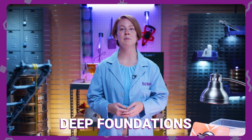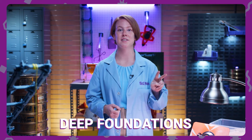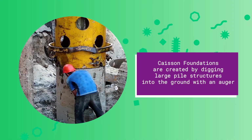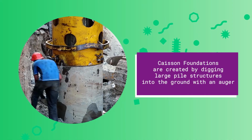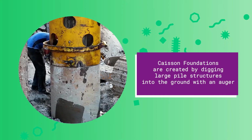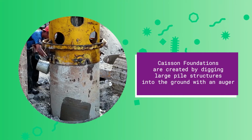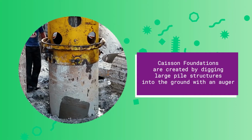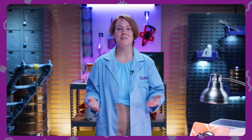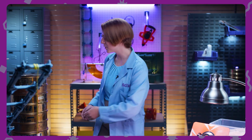Deep foundations can be broken down into 2 categories, pile foundations and caisson foundations. We can learn what a caisson foundation is by understanding how it is constructed. To construct a caisson foundation, a deep hole is dug into the ground using an auger, which is a tool that is used to till soil from deep into the ground and bring it up onto the surface. You've seen augers in smaller scales, which are used for farming and for setting fence posts. You might even have one in your garage or shed, just like the one that I have here.